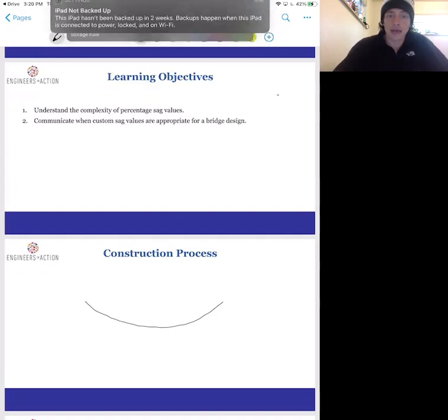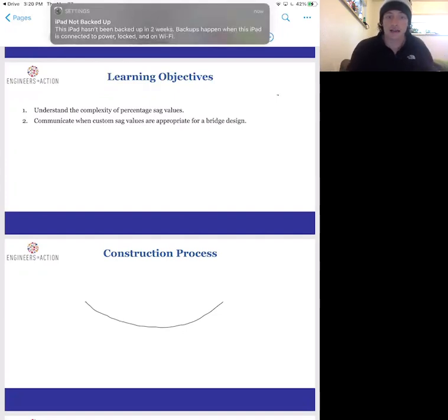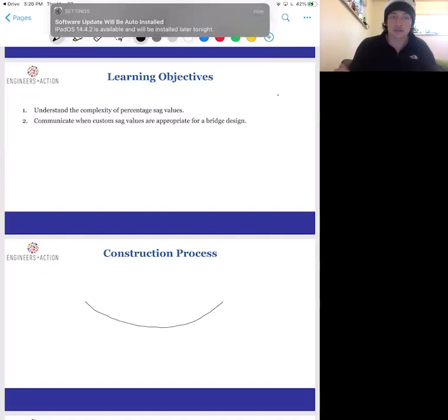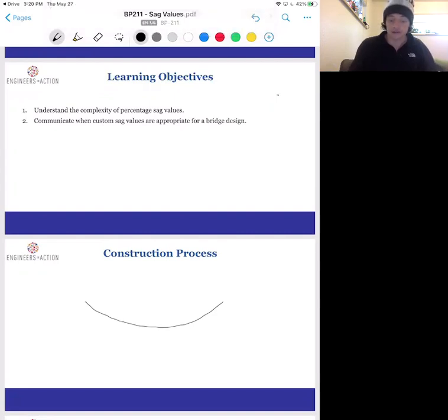We don't end up calculating a construction Sag, but this would be an even smaller percentage. We originally hoist the cables to this construction Sag, then let them settle to the hoisting Sag. So I'll put that in as this dotted line here, of what we'd actually need to hoist the cables so that they would settle to the hoisting Sag under their dead load weight.